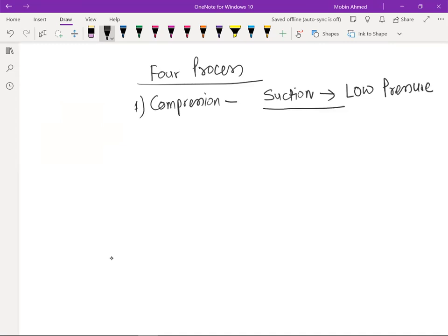And that's why sometimes we say this one is an LP line or suction line. So what is coming to the suction? The LP line is supposed to have only the vapor, that is what we say in general language, gas. Only the vapor is supposed to be coming to the suction line.